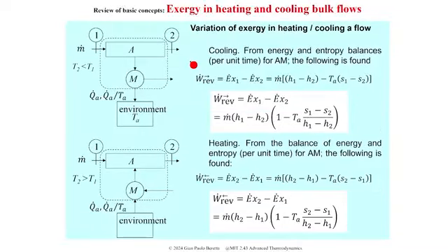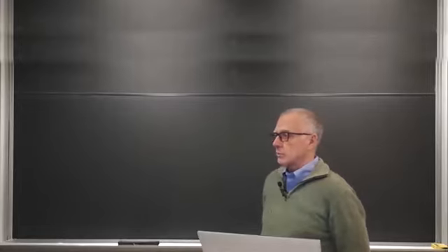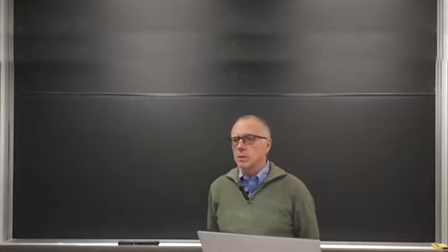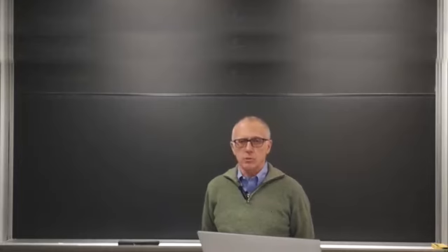So that means that if you combine those two ideas and you consider a flow that you want to change from a bulk flow state 1 to another state 2, depending on how these states compare, you may be able to do that while extracting some work, or you may need to spend some work to do that change of state.